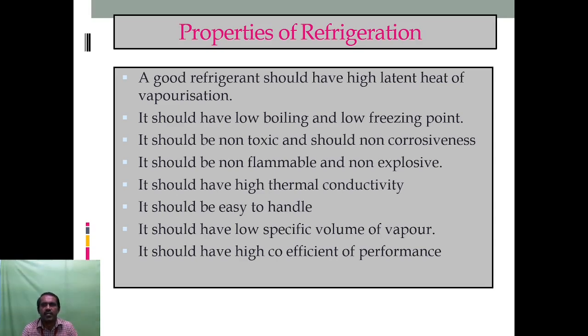And the properties of refrigerants. A good refrigerant should have a high latent heat of vaporization. Already I told, the latent heat is the property of the liquid refrigerant. Next, it should have a low boiling and low freezing point. Next, it should be non-toxic and non-corrosive.